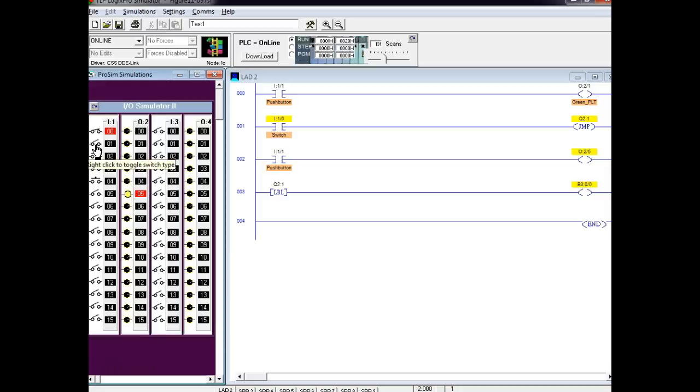Well, so it's not doing it, yeah. Okay, here comes a scan right here. Okay, and this is true, so what are we doing? Okay, we're jumping right here. Well, this says this light is supposed to be off, but yet it's still on. Why? Because we jumped over it, right? Okay, so let's take the jump out. So what's the jump? The jump is 0. Okay. All right. Notice it turned off instantly.